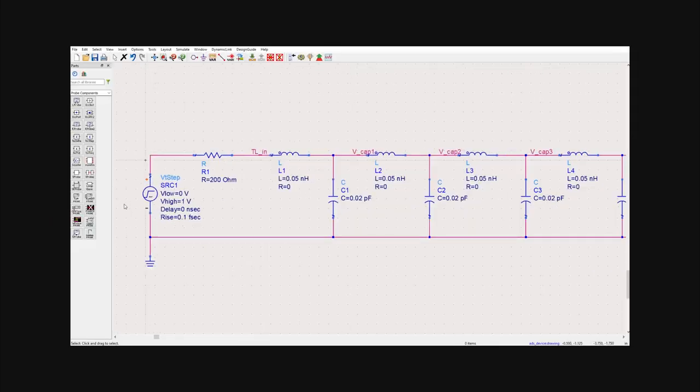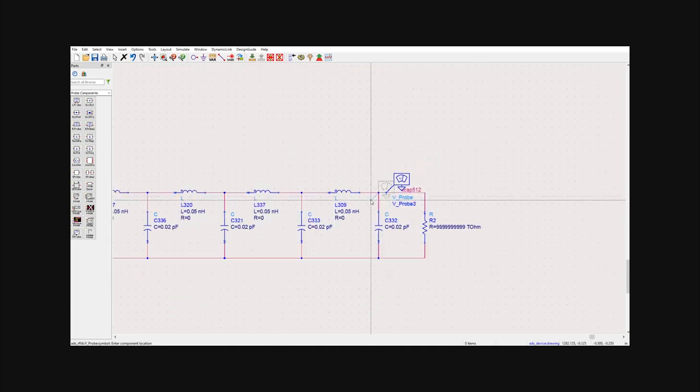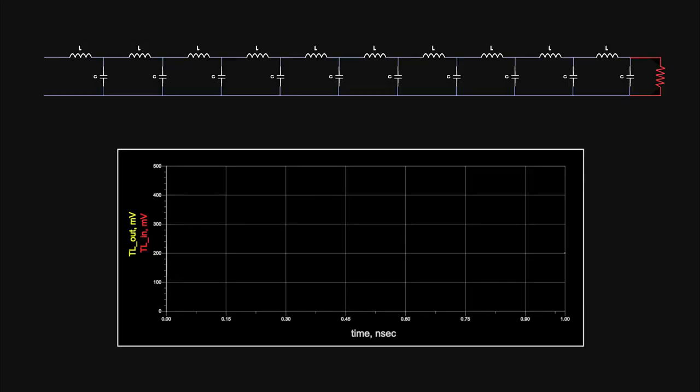To see the effect of reflection, let's tie the input and the output nodes to the oscilloscope, where the line is terminated with different kinds of loads. When the line is terminated with a 50 ohm resistance, the same as the characteristic impedance, the input of the line settles to 0.2 volts. That 0.2 volt signal will propagate through the line, charging each capacitor one by one to 0.2 volts till reaching the load. The voltage at the load end is zero until the signal reaches the load after about 510 picoseconds of propagating, and then settles to 0.2 volts.